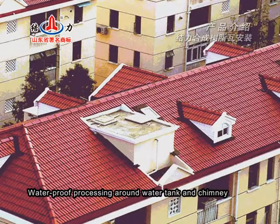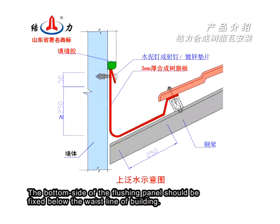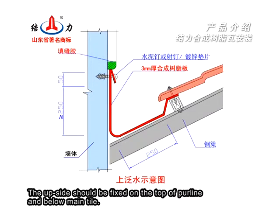Waterproof processing around water tank and chimney. Flushing panel around the water tank and chimney can be made of metal sheet and synthetic resin sheet. The bottom side of the flushing panel should be fixed below the waistline of the building. The upside should be fixed on the top of the purlin and below the main tile.